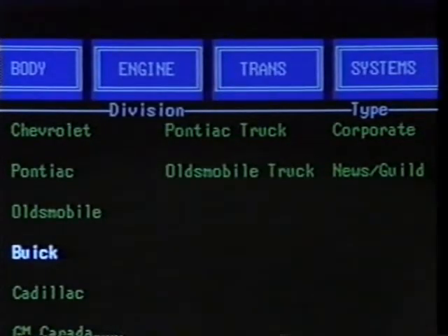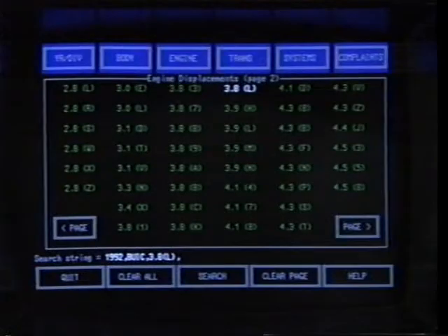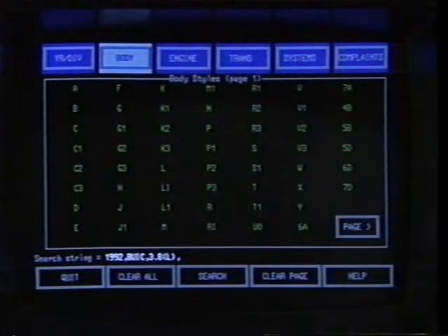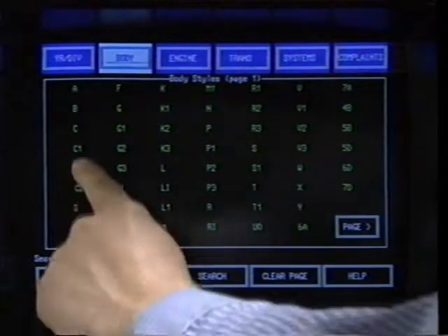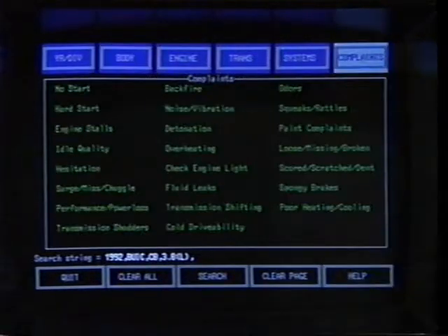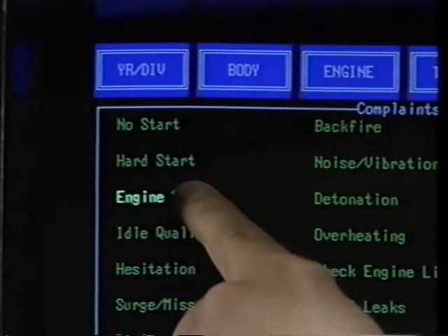Next, select the type of engine or transmission model, depending on whether you are searching for an engine or transmission-related bulletin. In some cases, a body style should be entered, but this may limit search results. When looking for a suspension or brake system bulletin, body style is more important than engine type. An engine or transmission bulletin is probably not specific to only one body style. Finally, the symptom is entered.